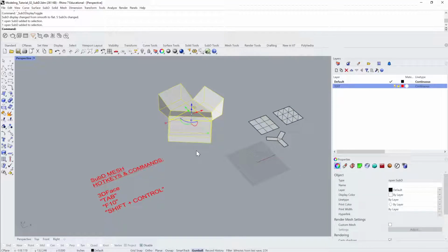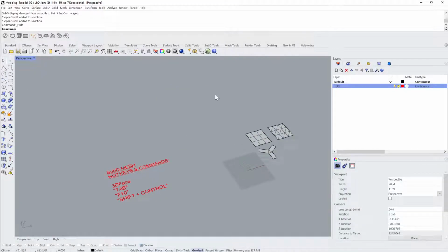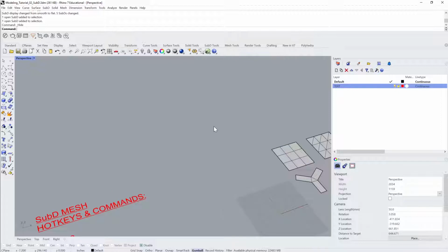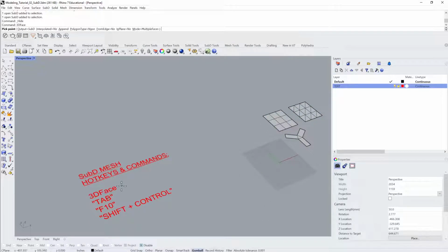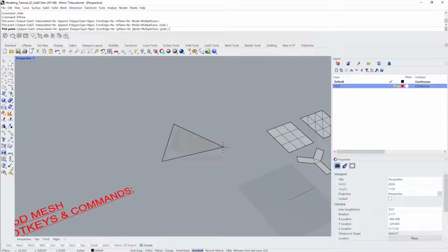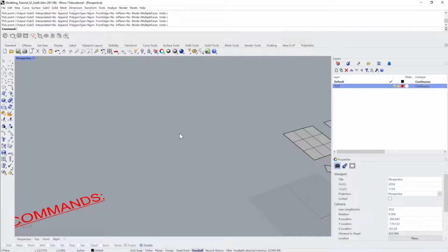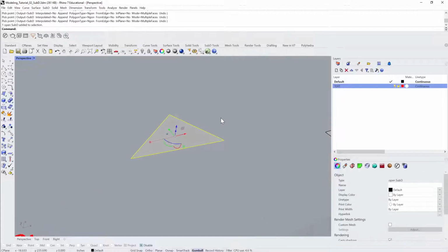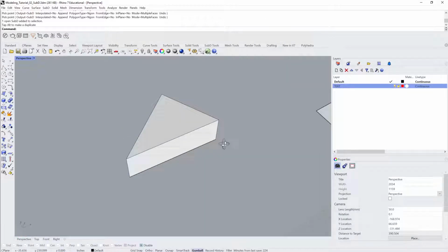I guess I also want to, at this point, let me just hide that. And let's talk about one other way of extruding. So 3D face is the command. So again, the first one in the list here, 3D face, is the command for creating a SubD. And then, let me finish that command. Enter, enter, okay, we have it. And I have the SubD, and I can start extruding it up like that. You'll see that it leaves the bottom open.